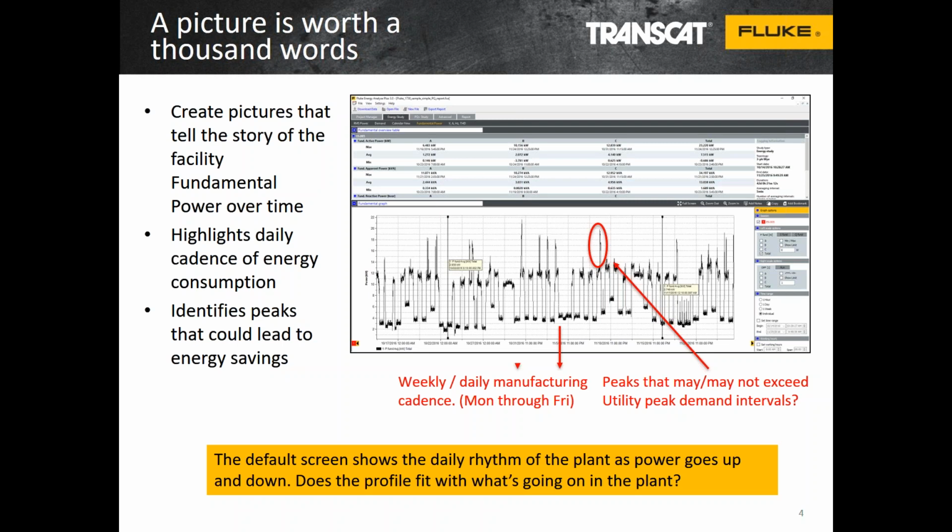And often it's because the system's had lots of adds, moves and changes made to it over a long period of time. So we've found out things where the users have asked for cooling during the summer, and they get that because they're in a hot environment, and they install some chillers to cool down the work area, and they end up running during the winter. And at the same time, they're not really well controlled, and they're putting on heating during the winter. And then they have these systems working against each other. We also had systems which were venting when they didn't really need to, so they were taking heat out of the environment where people were working, and then we were compensating for that using heating.